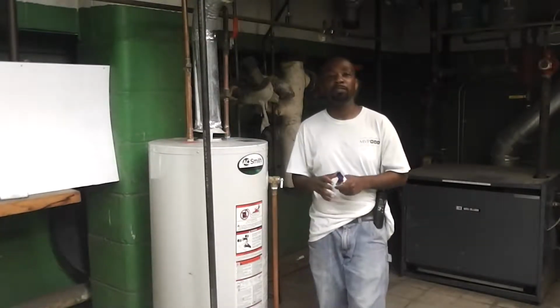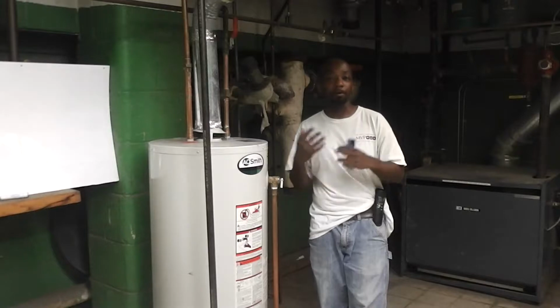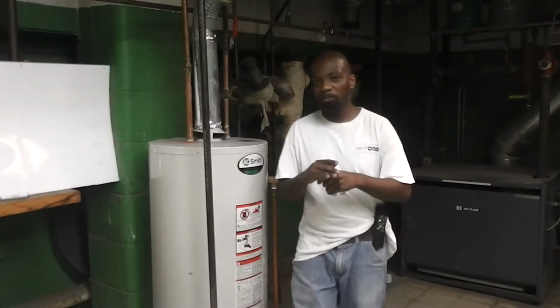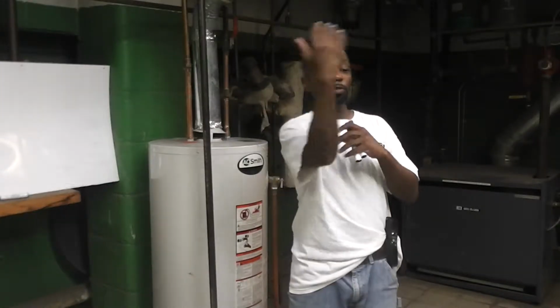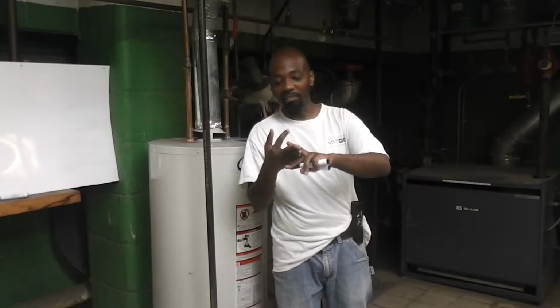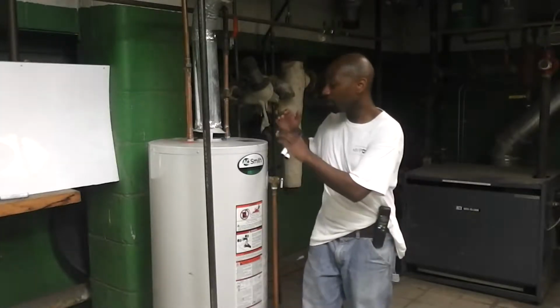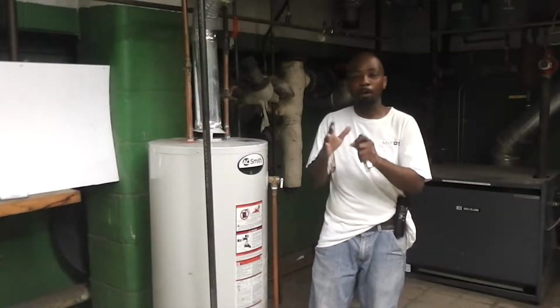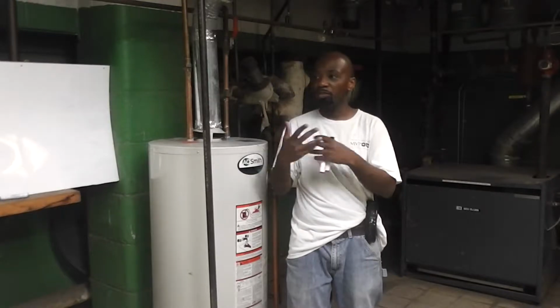The first thing I want to do is figure out the worst case scenario for this place. To do that, I want to see how the pressure in here compares to what's going on outside, naturally. I'm going to go around the house and make sure that anything that can make this place more negative, the exhaust fans, dryers, anything that can suck air out of here, is either off or closed. On top of that, all these combustion appliances are off as well. I want to figure out what that pressure difference is in a natural setting. So let's do that first.